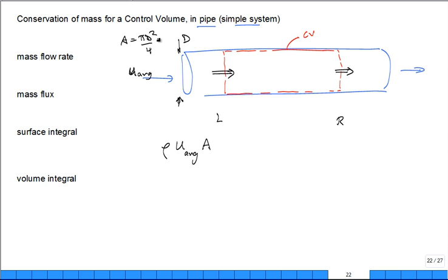Is it precisely 2 inches? No, but it's a 2-inch pipe. Go buy it and check it out. Get a micrometer. A 10-inch pipe isn't typically precisely 10-inch ID, but it's very close. Somewhere along the line they get precise and it matches up. This is mass density rho, and Q is the volume flow rate, and then U is the speed, A is the area, and that's equal to the mass flow rate, m dot, equals rho A V. True? Good. But also, it's equal to rho Q, is that right?